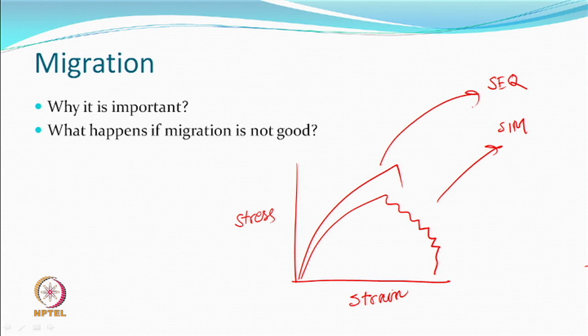Now, this curve, as I said, the stress strain curve, is a simple experiment that can also give you information. What this information says is a staggered break. That means some filaments are breaking first, then the others, then the others, then the others. What you have done is that every filament has a different kind of property. Now, why? We thought that twisting was a good idea, so that every filament on an average length along the length of the yarn would get the same treatment,